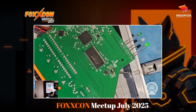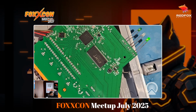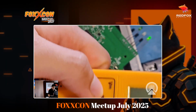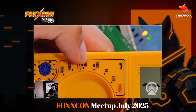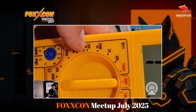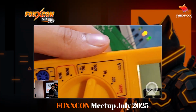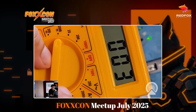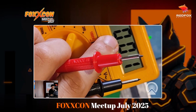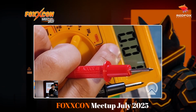For that, because we want to now measure voltage and not just if electricity is being conducted from one end to the other, we are going to switch our modes. By the way, this symbol you see here is for DC, and this is the specific range that you want to measure. The voltage range, this is the smallest you could start, and it goes higher. If I just turn there, you see the dot is gone right now. This is just milliamps. This is your voltage. Let's say if it's 3.3 volts, then 3 will be here and 30 will be here, because there's a point in the middle. That's how you measure voltage here.